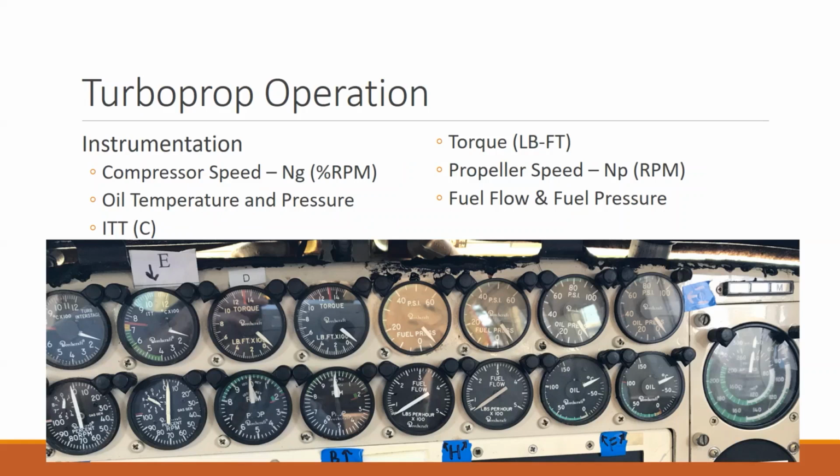So this one, the top left, you have pairs of dials, and they're arranged as left engine, right engine. So the top left dials, the ones that are labeled E there, there's a left engine ITT and a right engine ITT. It's interturbine temperature. Okay. Temperature is pretty important. We want to know how hot our engine is. Okay. Below that is our gas generator speed.